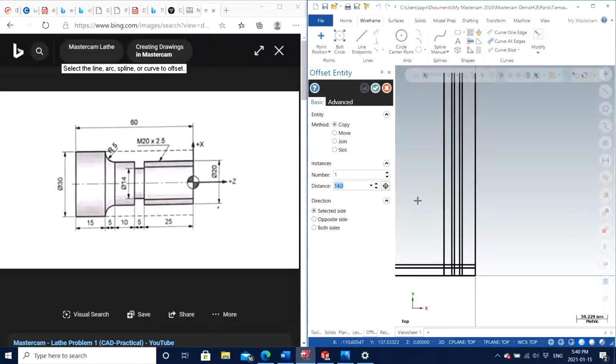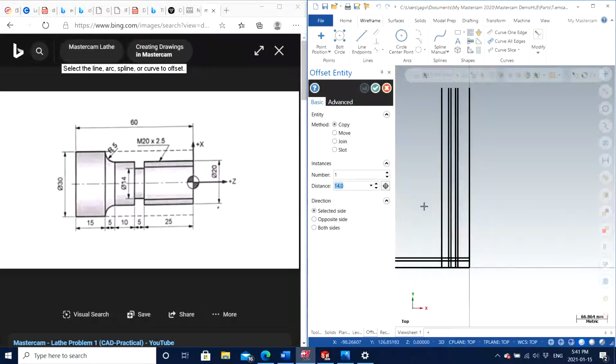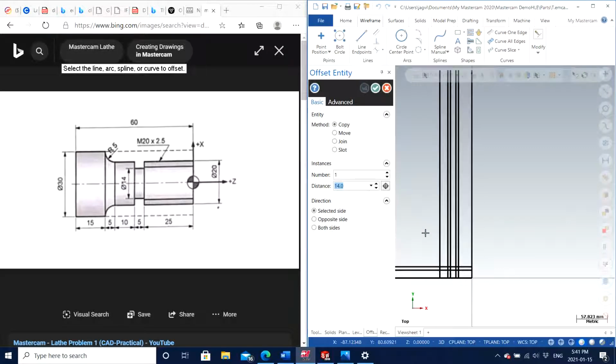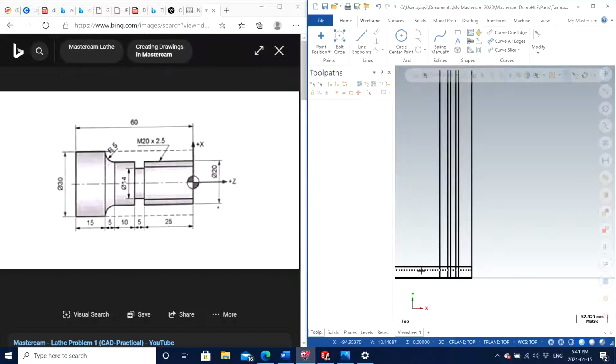Just to let you guys know, sometimes it can be really confusing, just like right now. I think that I misunderstood the drawing and I started making right away. So that's my bad. I just wanted to let you know that this is a very common mistake that can easily happen. So always divide the diameter by 2 and don't forget to do that, because we are actually making just one half of the actual drawing. We are just trying to make the upper half, not the lower half.